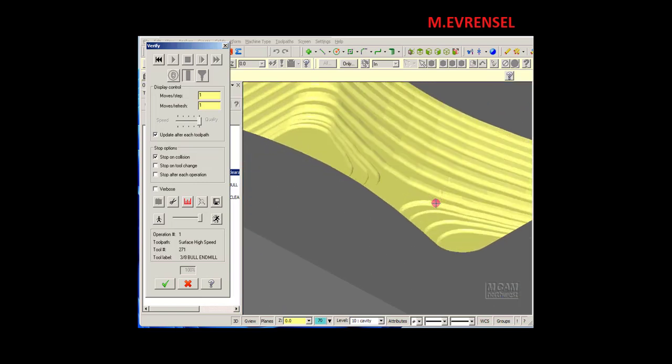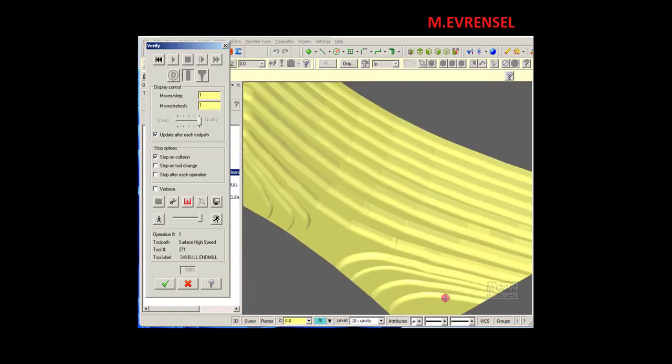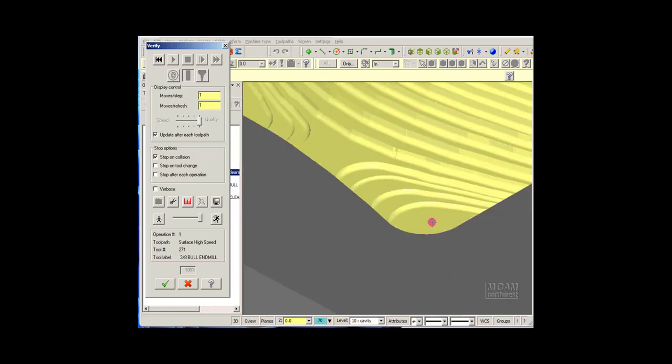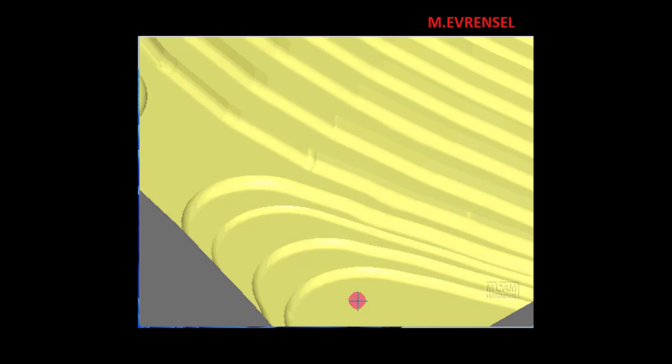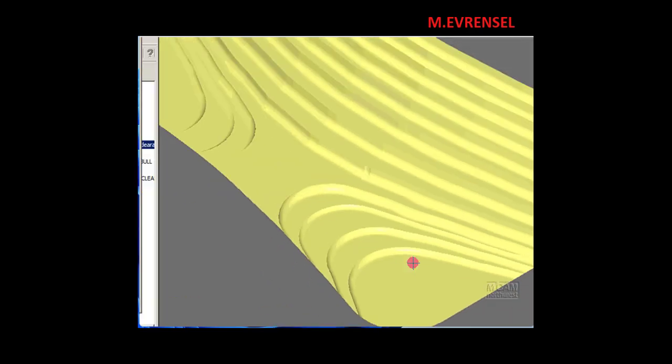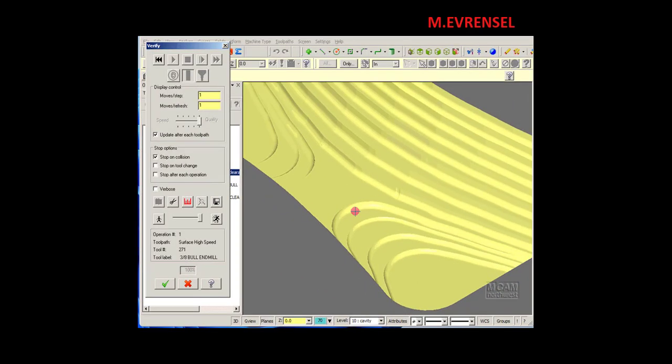But then if we zoom into the bottom here, we can see our add cuts feature kick in. Now what that's allowing, where the slope tapers off and it's a very shallow angle, the 16th inch step down could leave a pretty large stair there and uneven material at the bottom of the part. So add cuts is activated automatically and adds a few extra Z passes there to leave us with a much more consistent remainder of material.